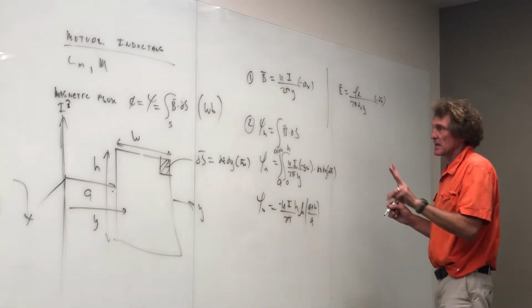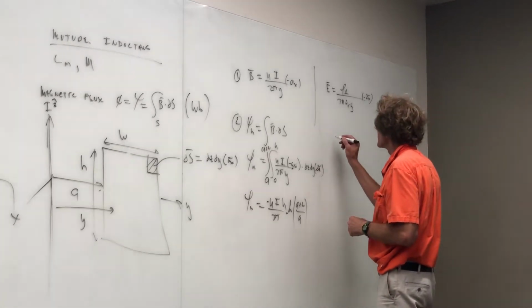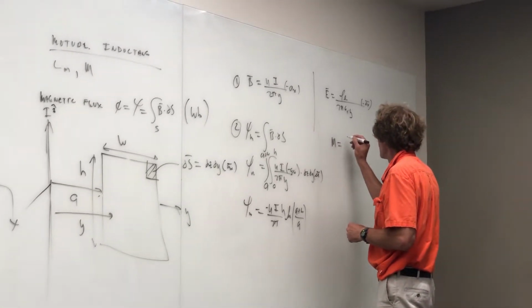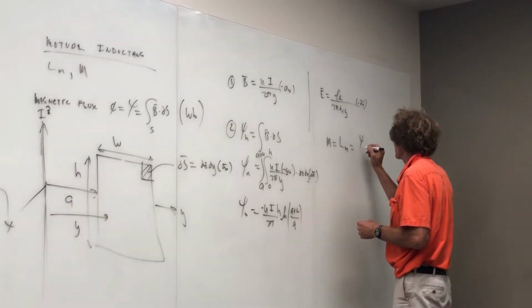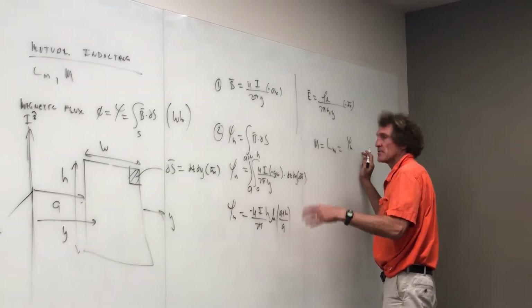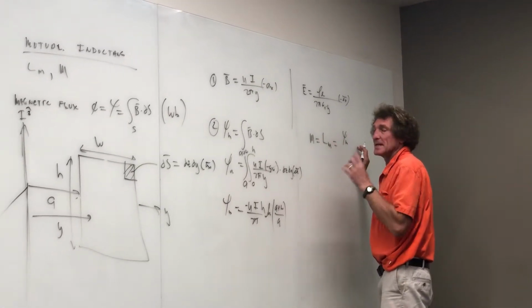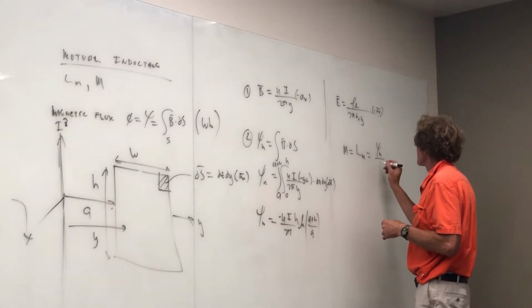Now that's the second thing, so we've got the magnetic flux. Third, we find inductance. The mutual inductance, either this symbol or L sub m, either one's appropriate, is simply the magnetic flux created by the first conducting system that penetrates or is within the second conducting system. And then we divide it by I.